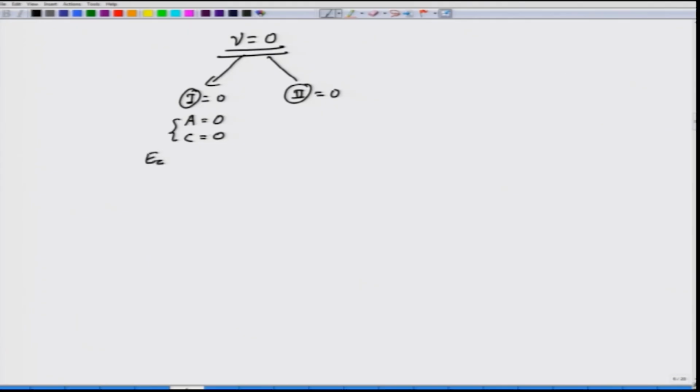So, what we have seen is that when nu equal to 0, Ez will be completely 0 if you assume the first term to be 0. Ez will be 0 both in core and cladding; in fact, Ez will be entirely equal to 0. Since Ez equal to 0, such modes are called TE modes, and the order of these TE modes always has to be 0. That is the first order; the other order will come out. So, you have TE 0 and M, I will shortly tell you what M is. These modes are essentially called TE 0M modes.